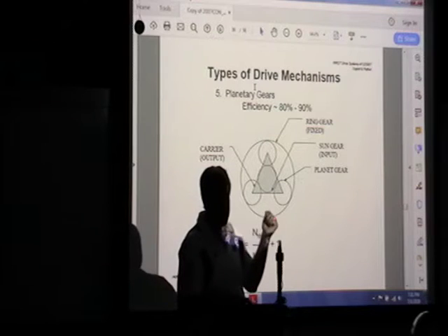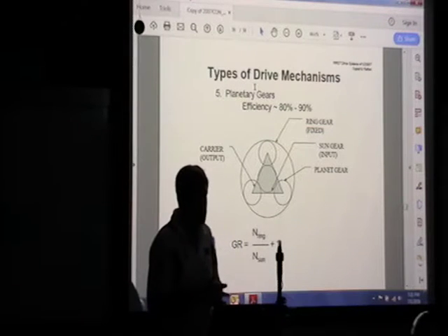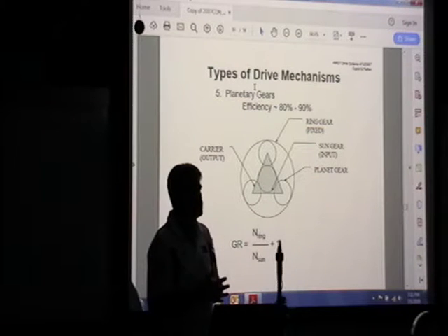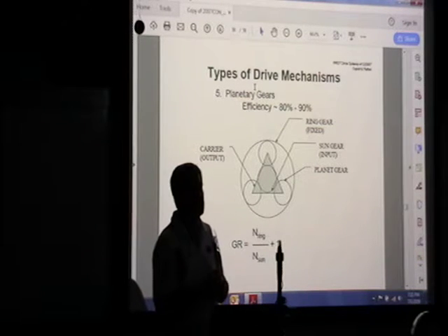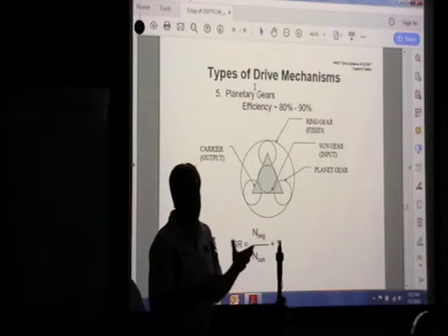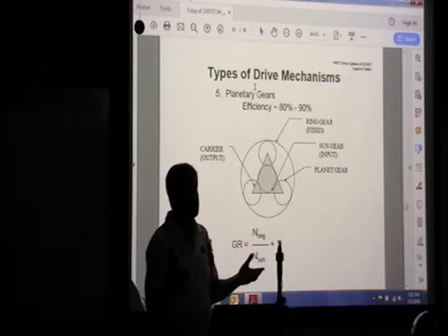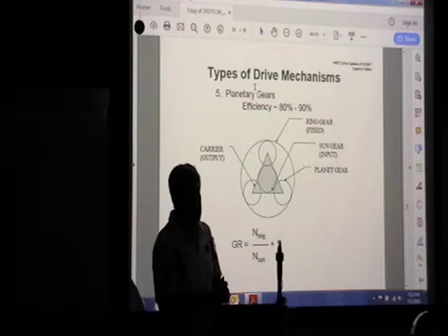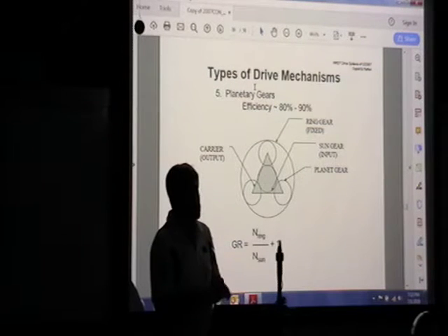These are kind of cool in the packages that they give out because you can get different gear sets for one gearbox. I don't know, was it Versa? Versa is the one we've got, and you can get anywhere from a 3-to-1 to a 10-to-1 and put in that same gear set, and you can stack up to 3 of those. But you can also get too much power in that too.